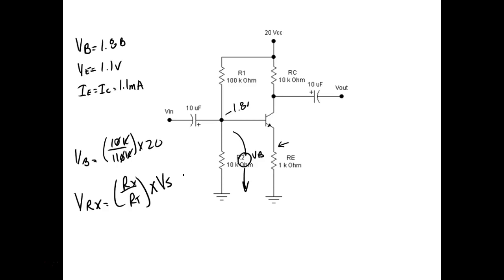And what's nice about a transistor amplifier is you can almost usually calculate RT in your head. I can look and say, well, 1/11 is going to be pretty dang close to 1/10, right? So if I put 2 volts up there, it would still calculate out to be okay. So what's nice about the voltage divider formula is you have a pretty good idea of what that voltage should be. Just looking at a 1/11, I knew this would be slightly less than 2 volts, without even picking up a calculator.